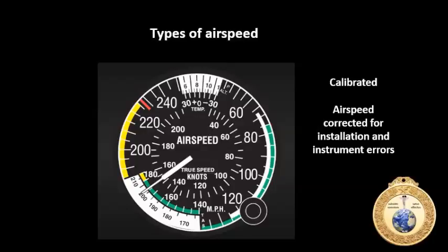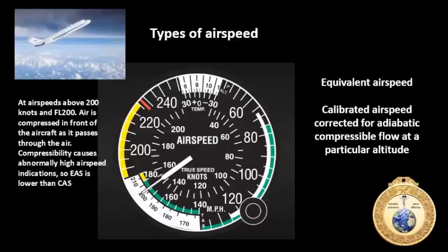Alright. There are many different flight attitudes where you will not get the correct indicated airspeed. So there's a calibration to help you with that, to make the adjustment because of the plumbing and associated things of installing the instrument in that position and stuff like that. There's going to be some errors associated with it. Not major errors, but we just want you to know it's an instrument, and in instrumentation we want to try to be as accurate as possible. The next airspeed we're going to talk about is equivalent airspeed. Equivalent airspeed really deals with high performance aircraft.